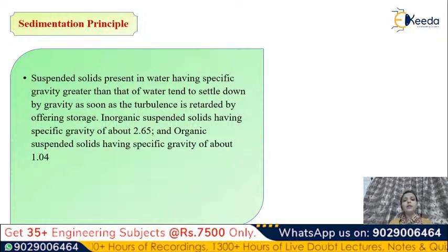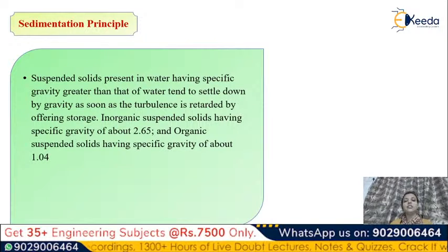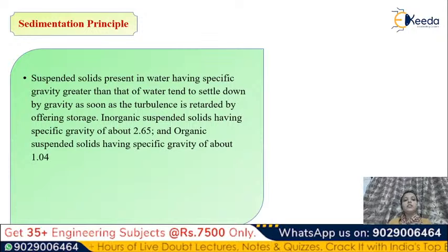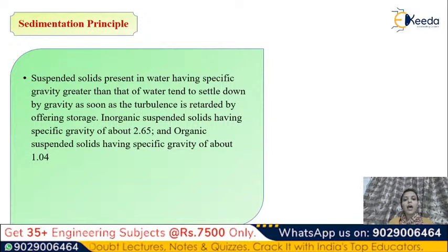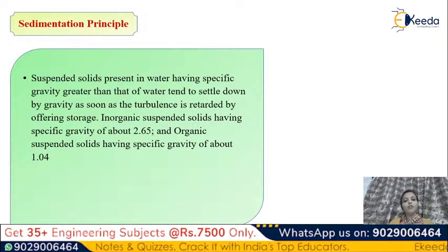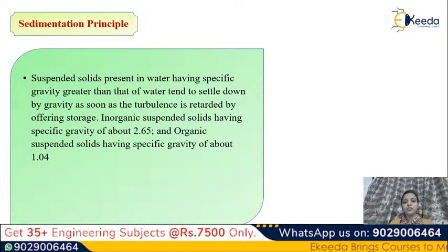So what is the principle of sedimentation? Sedimentation is based on which principle? The suspended solids present in water having a specific gravity greater than that of water tend to settle down by gravity as soon as the turbulence is retarded by offering storage. So there are two important factors. First is the gravitational force, and second, we are retarding the turbulence. That means we are providing sufficient detention time and reducing the velocity so that the water becomes stagnant, and because of that the gravitational force works.